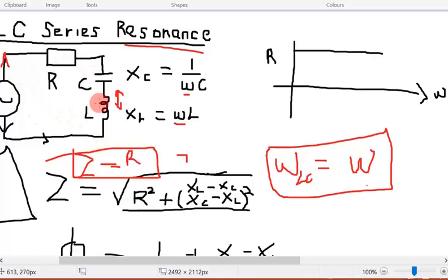If they have the same frequency, this one pushes and this one pushes in this direction, then they will have maximum flow. But if they don't have the same frequency, this one pushes current in this direction, this one pushes current in the opposite direction, the effective current flowing through will reduce. So resonance is achieved when they have the same frequency. This is the natural frequency.